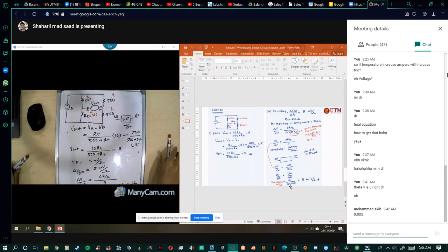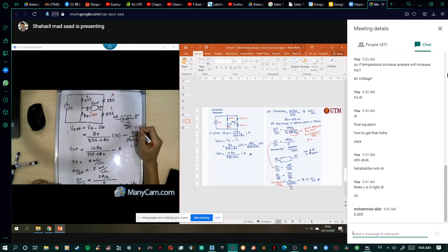Okay. So by having this sensitivity, that means whatever change of delta R you get, for example maybe 1 ohm, you times with 5, now you can get 5 millivolt here. And after that, if you got 2 ohm here, right?